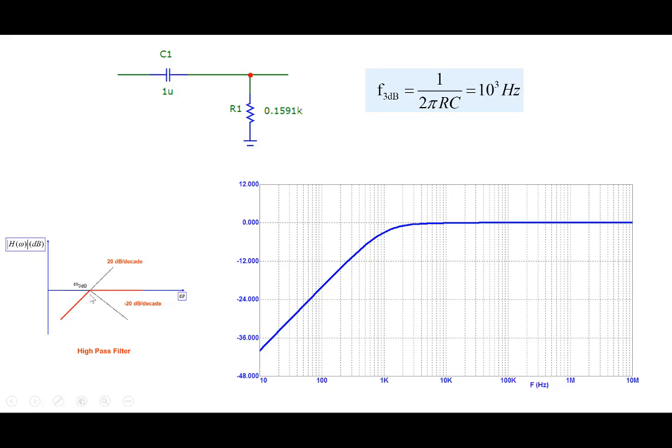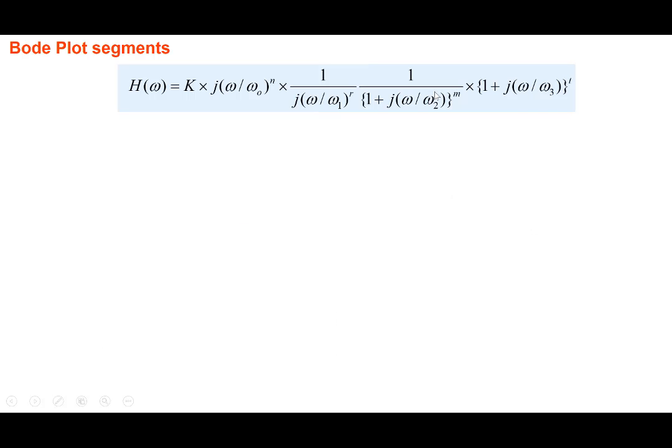And we said that we are not sketching things very well at this particular point here. So you can see that our cutoff frequency is 1K here. So at this particular point, what will be the magnitude here? Minus 3 dB. Please verify it: if I substitute numbers there, this will be minus 3 dB at this particular point here. That's why many times we call these frequencies 3 dB frequencies, cutoff frequencies. They are the point where it's 0 dB, and then at this particular point becomes minus 3 dB. This is where we have this 1 over 2 pi RC.